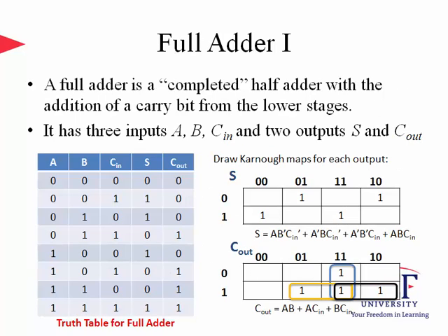Notice that the half adder is a nice tool for performing the binary addition operation, but there is something missing with it. Think about adding 2 sequences of binary bits. In that case, there are multiple stages of binary bit additions. It might be the case that the previous binary addition creates a carry that propagates to the current addition stage. In that case, the half adder cannot account for that.